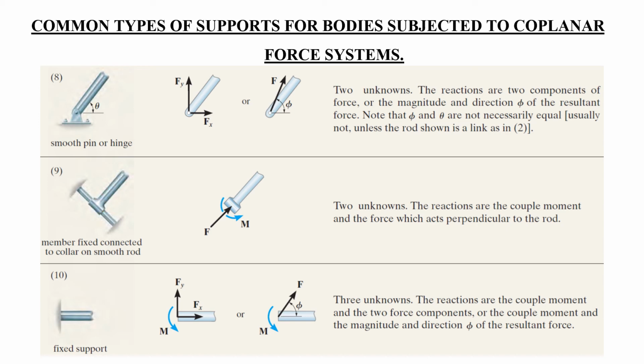Now, if you try and rotate this, it should not be able to rotate because it is going to be stopped here. Or if you try and rotate here, it is going to be stopped here. So now you can see in addition to this force, we are also adding the moment. Again, you can move this rod freely in this direction, so there is no force in this direction, but you cannot move it in this or this direction.